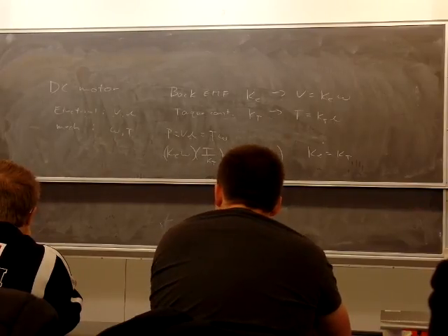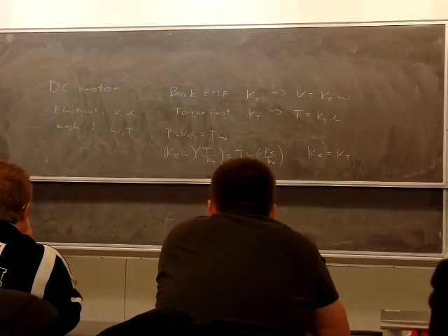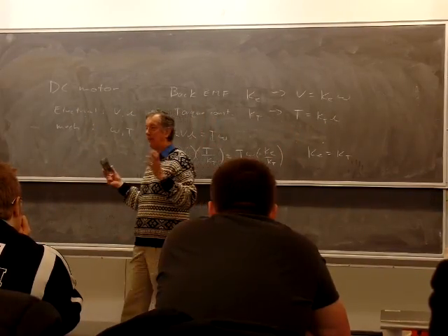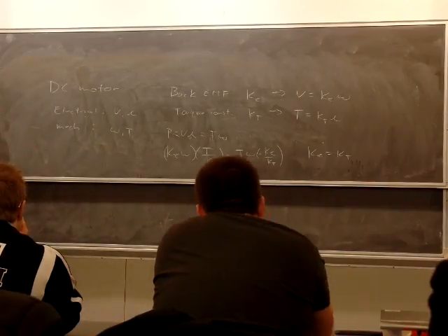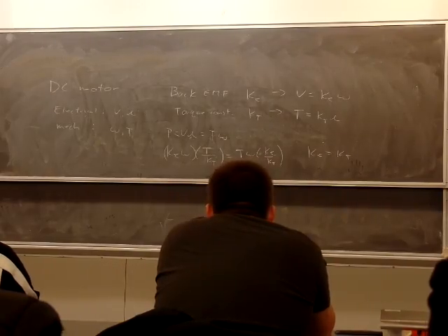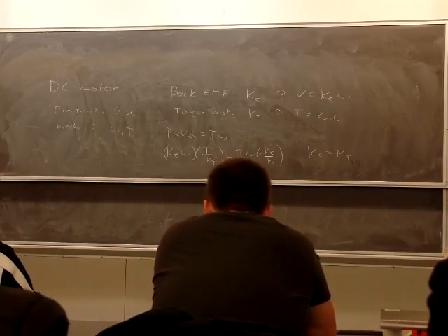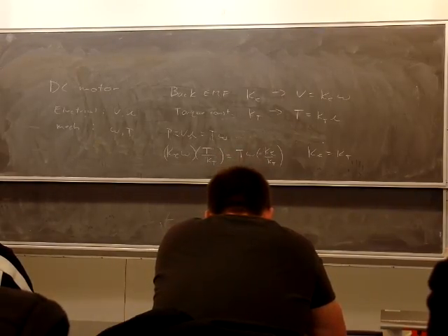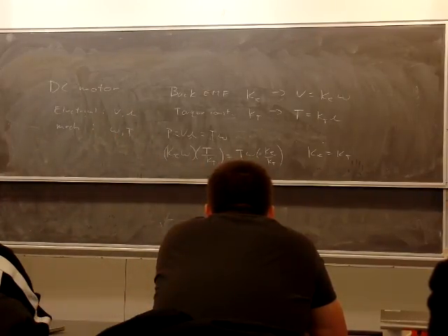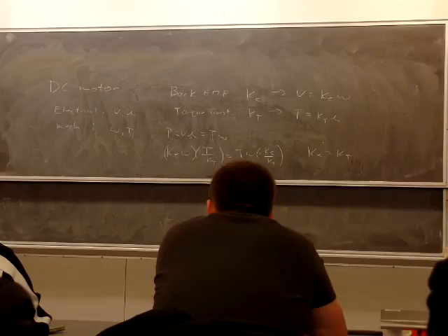The wrong units are the English American standards. All right? So in this country, a lot of times, torque is often listed in ounce inches. Speed is almost always what when you look at the catalog? RPMs. Are those SI units? No. You need to convert to radians per second and Newton meters, and it works out very nicely. Otherwise, you need conversion factors. Right? All right. Questions? Does that make sense?